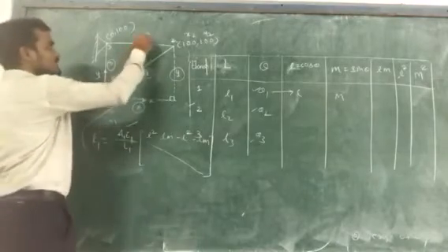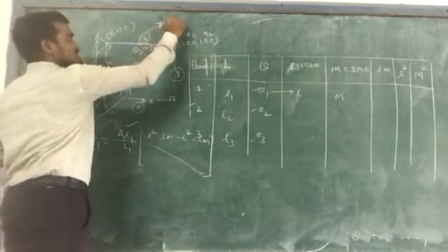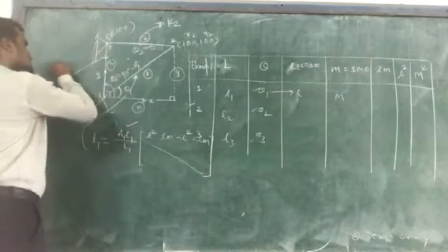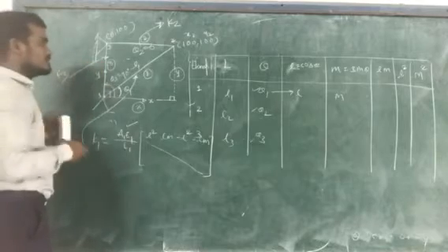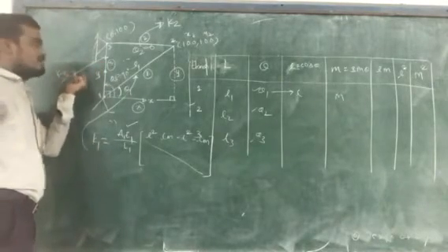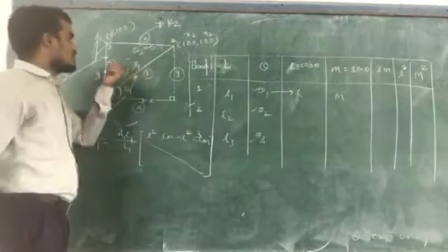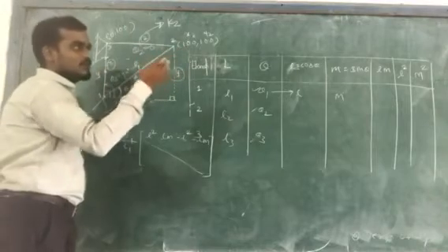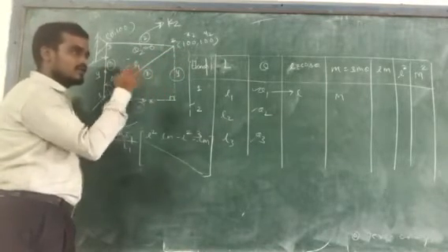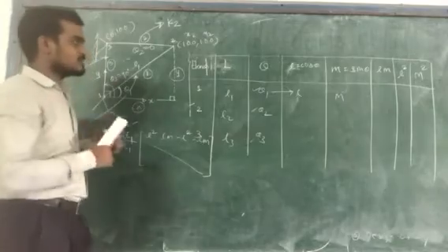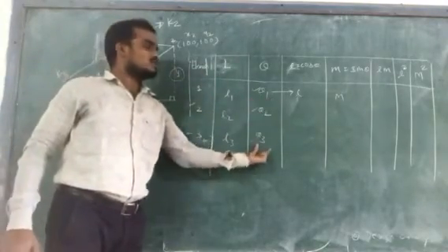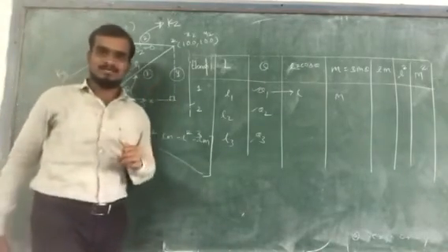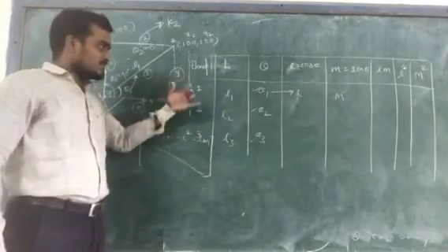Similarly, you need to find the elemental stiffness matrix for the second element, which is K2. And similarly, you need to find the elemental stiffness matrix K3 for the third element by using different material properties and by using l, m, l square, m square for theta 3. Because l, m, l square, m square, lm are different for different elements, since they depend on theta 1, theta 2, theta 3 values. So you will get 3 different elemental stiffness matrices.